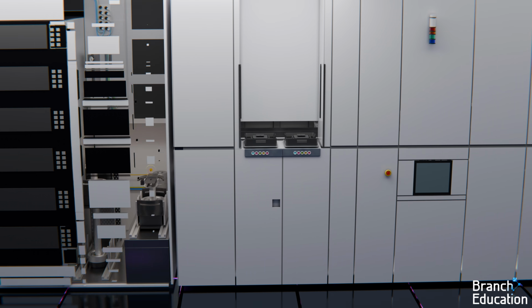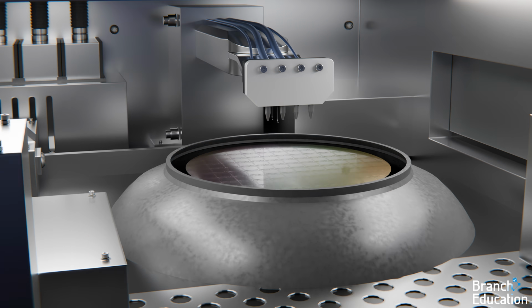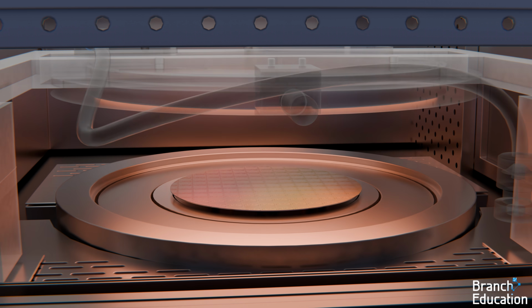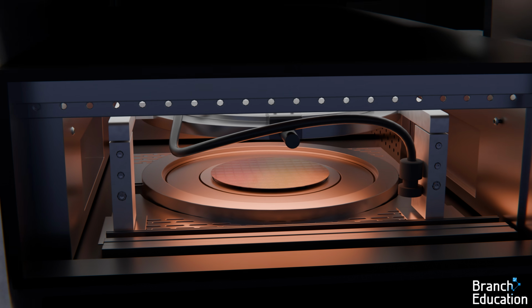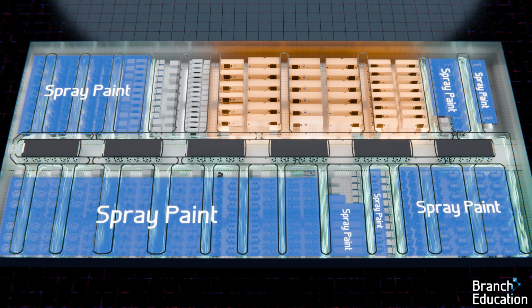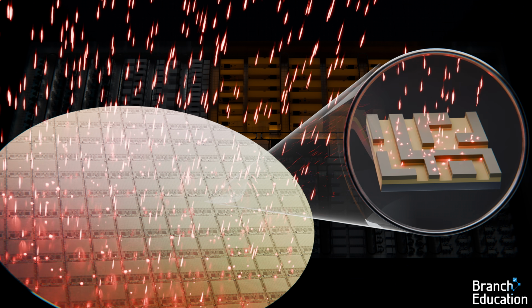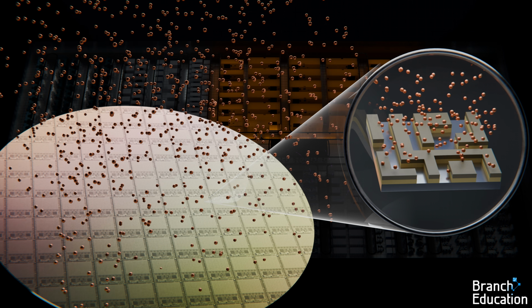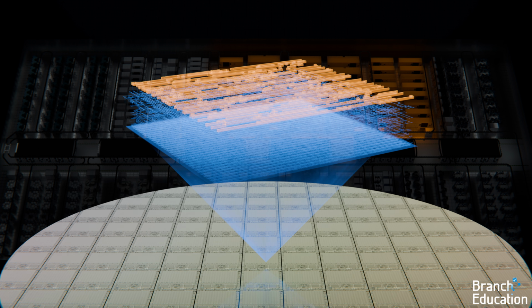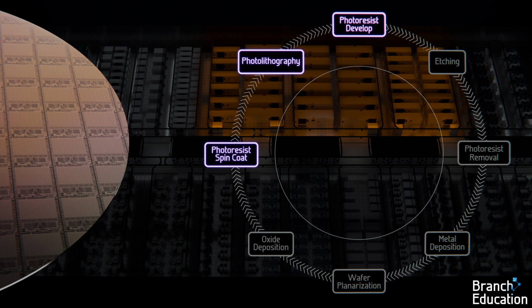Next, the wafer travels back to the track tool, where the modified resist is washed away using a developing solvent, and the wafer is heated to form a hardened stencil, or completed photoresist mask layer, on the top of the wafer. Now that the wafer is patterned, the wafer travels to the other spray paint-like tools in the fab, which are used to etch away the uncovered areas, implant dopants such as boron or phosphorus, or deposit a layer of copper, tungsten, or other metals, thereby building a single layer of nanoscopic structures. Note that there are additional process steps that we're not going to get into.